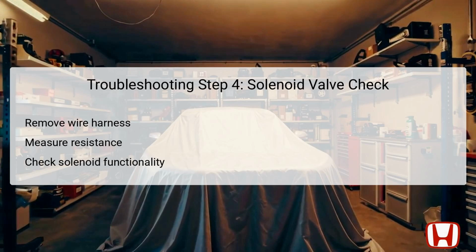The fourth troubleshooting step involves checking the CVT clutch pressure control solenoid valve directly to ensure it is functioning correctly. Begin by removing the solenoid wire harness to access the terminals. Once disconnected, measure the resistance across the 2 designated terminals of the solenoid valve using a multimeter. Under optimal testing conditions, the resistance should fall between 4.9 and 6.6 ohms to be considered acceptable.